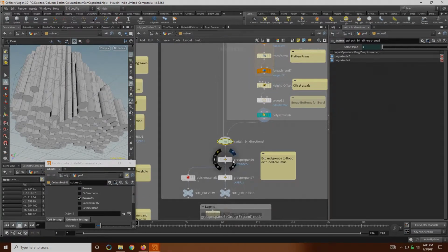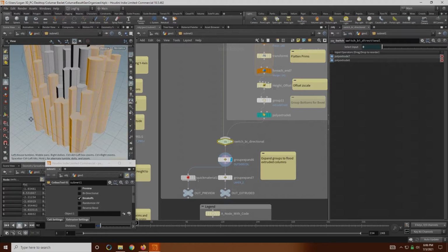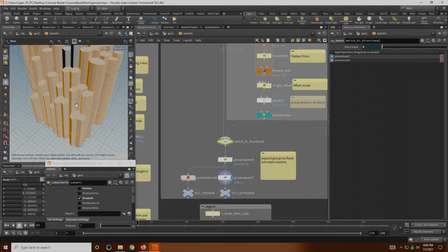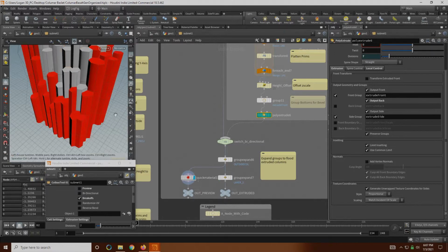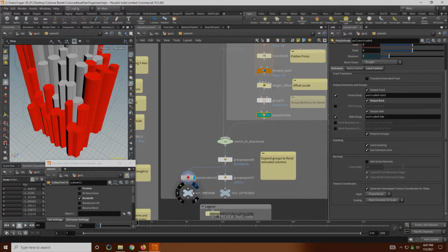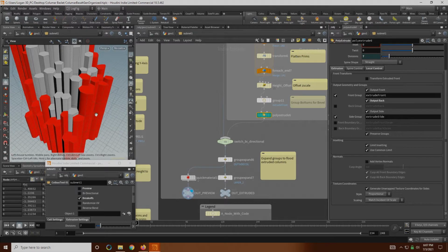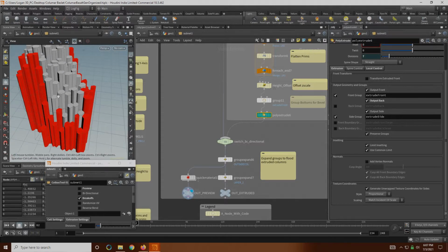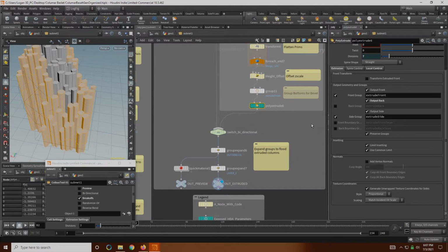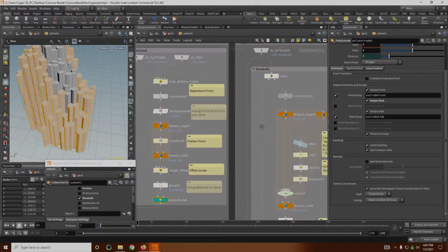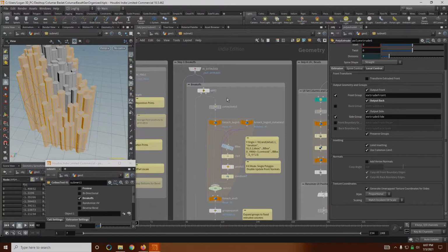And then we have the group expand nodes that I talked about earlier, just flood filling all the new geometry that those primitives generated from the extrusion node. And then one quick preview material and output to preview. This is just good for seeing what'll be broken away in the breakaway node, and it's a good, fast, simple representation of what the end product will look like. And then it's just output, and that's it for step 2. Moving right along to step 3, the breakoff node.